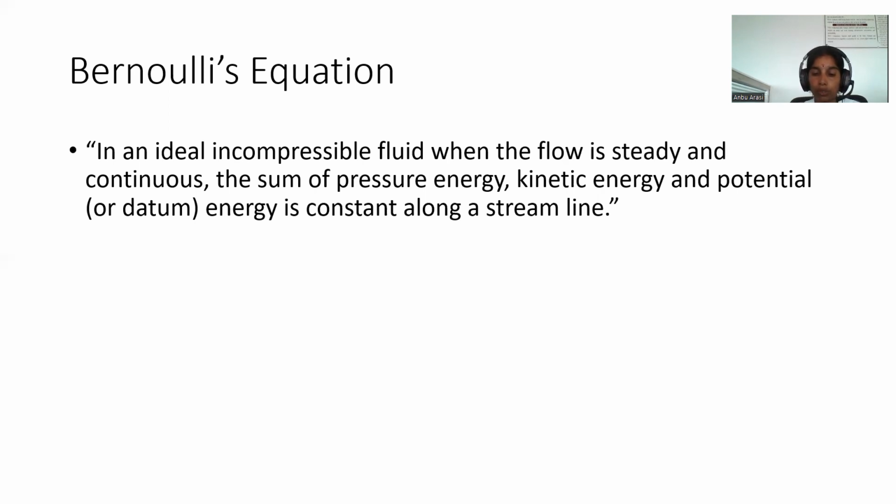These energies per unit weight of the fluid are: pressure energy P/(ρg), kinetic energy V²/2g, and datum energy Z. Mathematically, Bernoulli's theorem is written as P/(ρg) + V²/2g + Z = constant. The derivation of Bernoulli's theorem is covered in other classes.